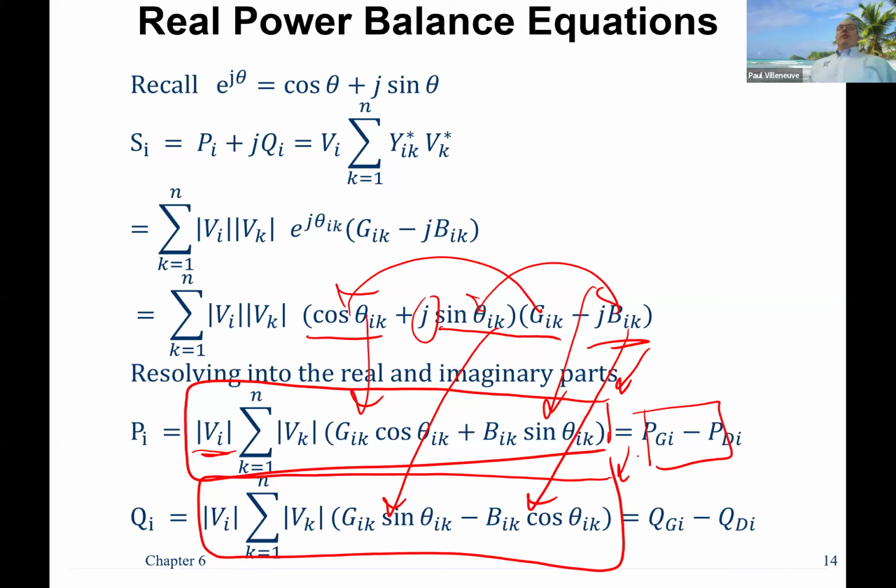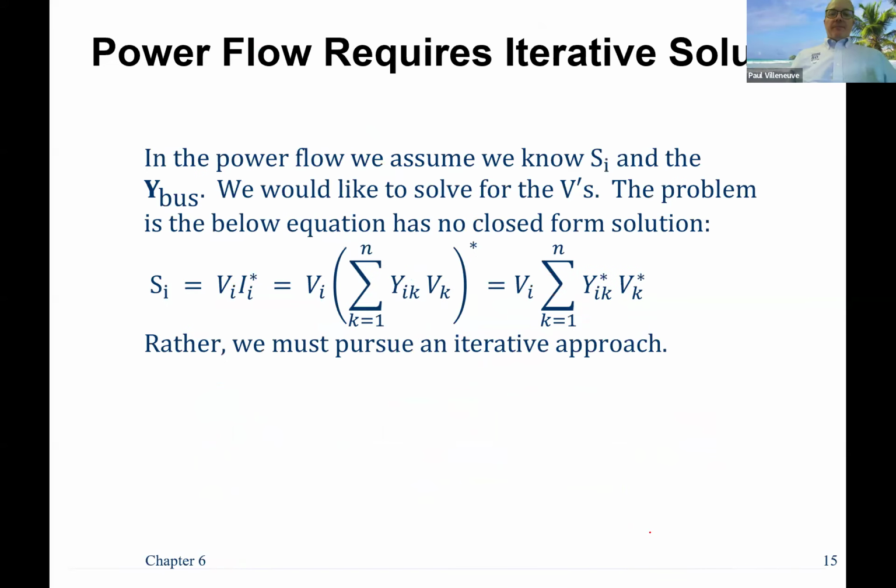They're not quite there, because if you remember with Newton-Raphson, we were always doing root finding. You remember in lab, we were looking for the value of x so that f of x equals 0. So you're solving for a root. All you need to do is subtract these two from both sides, and then you set the equations equal to 0. And those are your power balance equations.